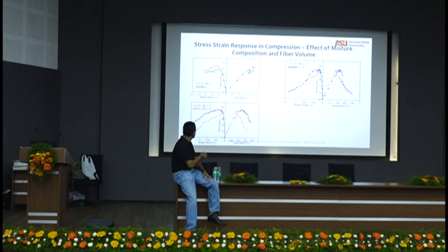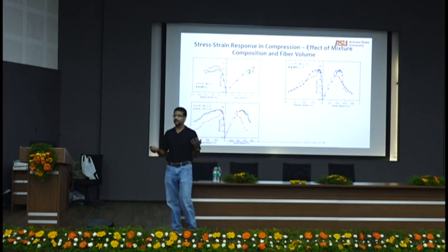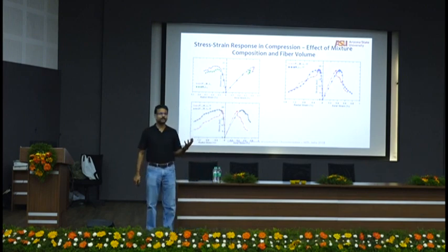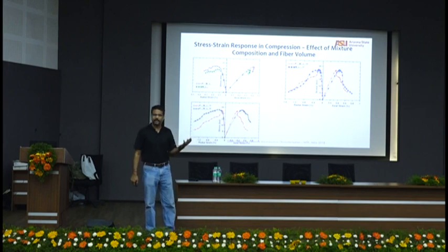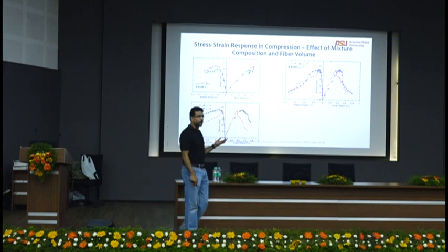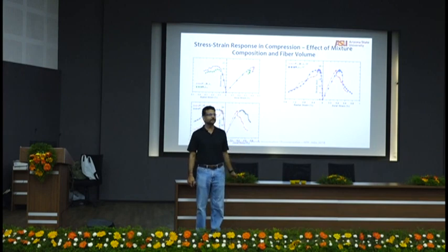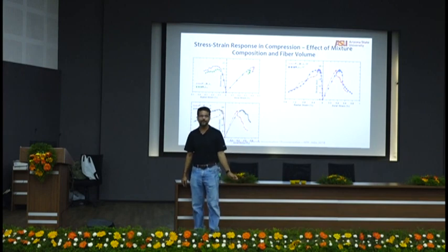So you get about 150, 160 megapascal strength, but you see that you have an axial strain of about 0.4%. Remember, when you do your reinforced concrete design, what is the maximum usable compressive strain in concrete? In Europe, India, and Canada it is 0.0035. In the US, it's 0.003.